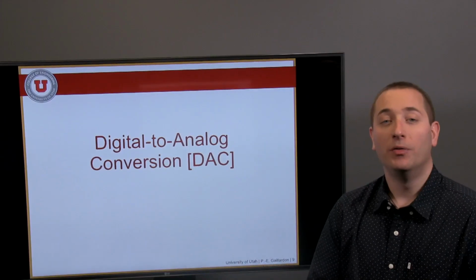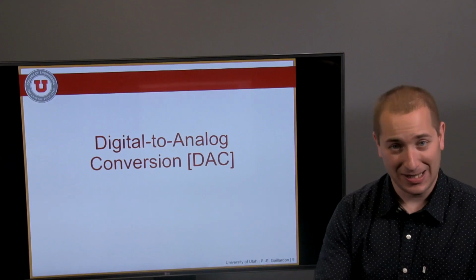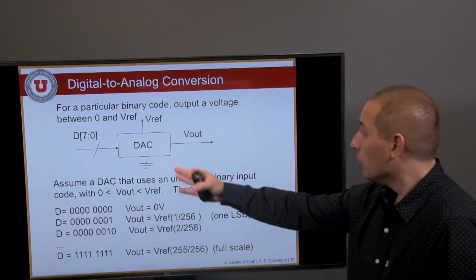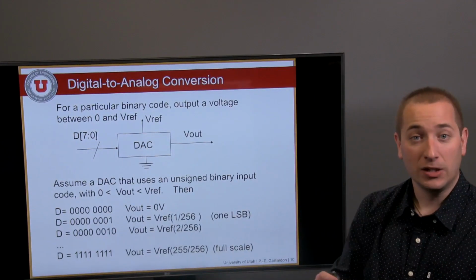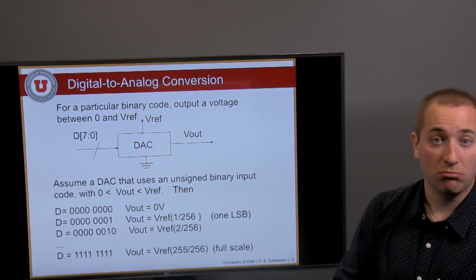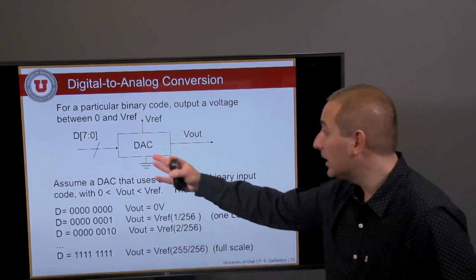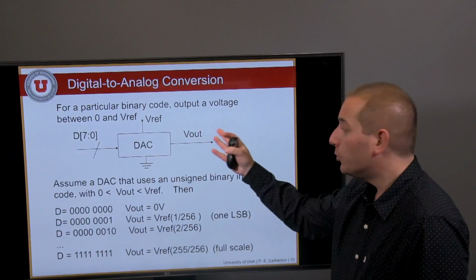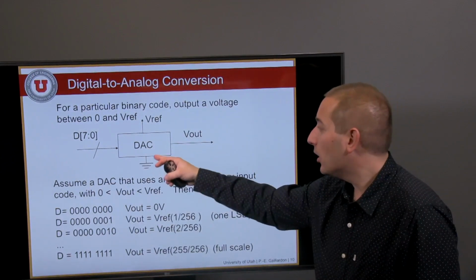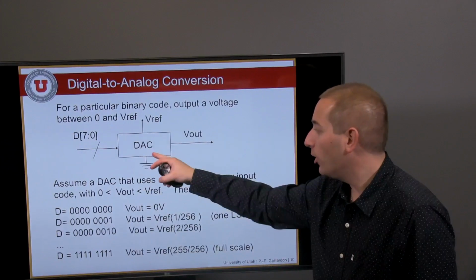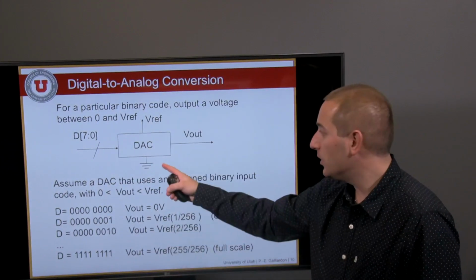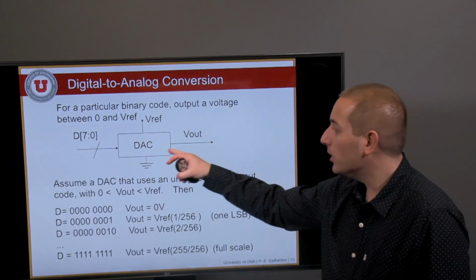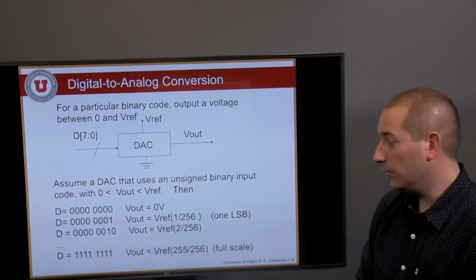We're now going to talk about digital to analog conversion, DACs. In digital to analog conversion, you are providing a given digital information with a given precision, in that case 8 bits, and your DAC module will generate an output value using a full scale between the bottom reference and the top reference, in that case 0 and Vref. And in between, it will generate Vout to be equal to the quantized version of this input.